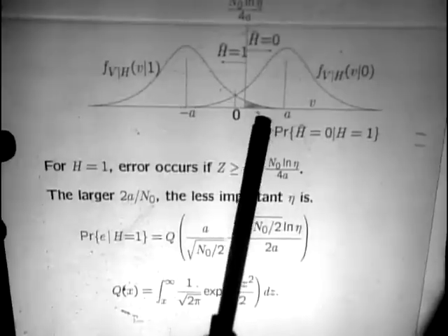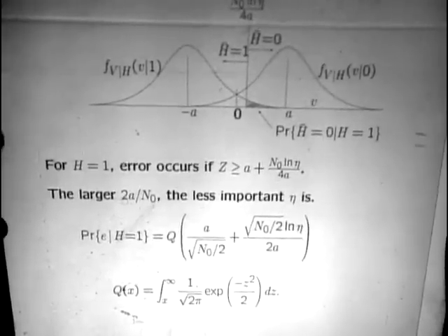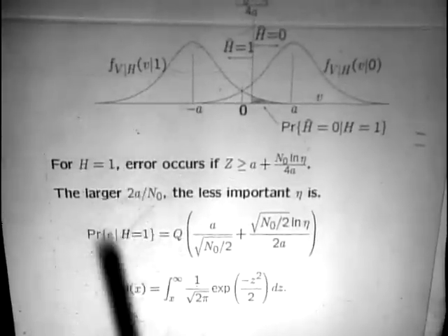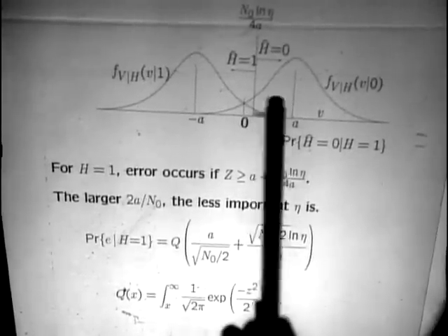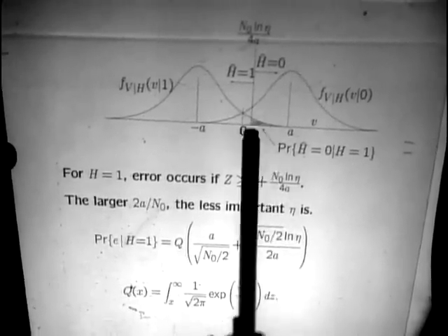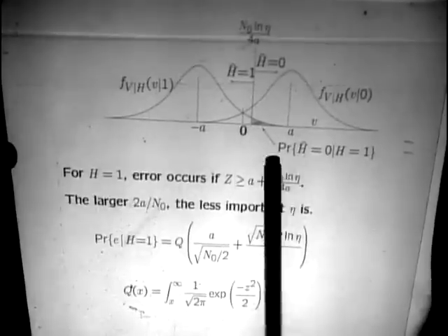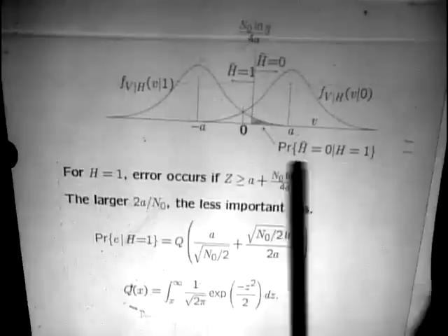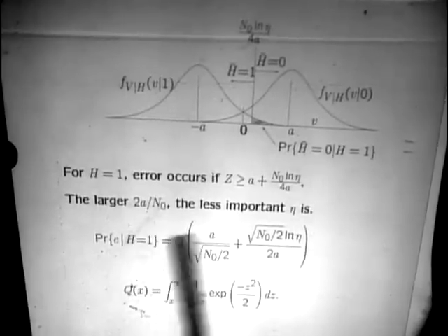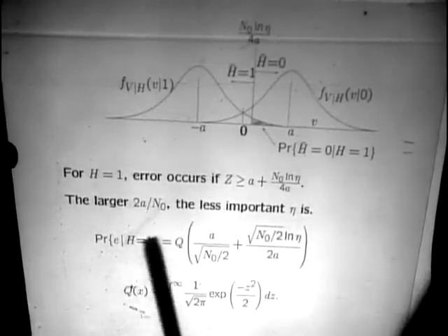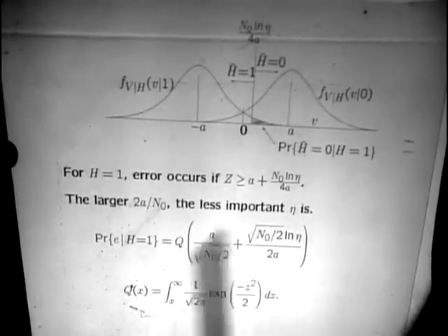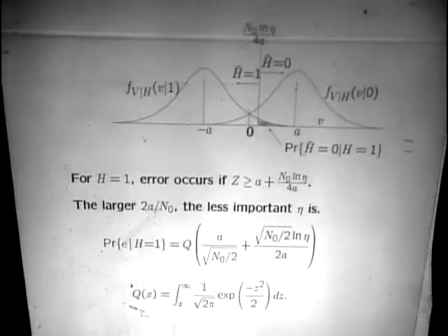I'm going to make a mistake. So in fact, the probability of error conditional on sending 1 is just the probability of that little space in there, which is the probability that I'm going to say that 0 occurred when in fact 1 occurred. So that's my probability of error when 1 occurs.